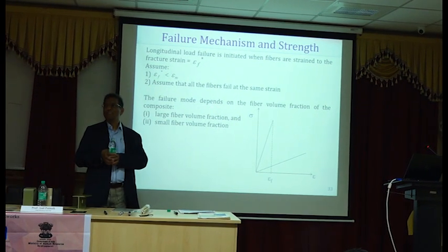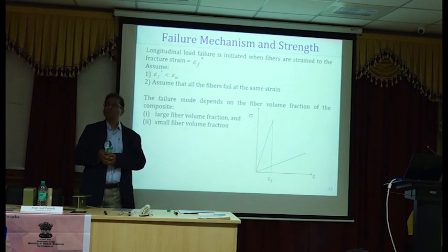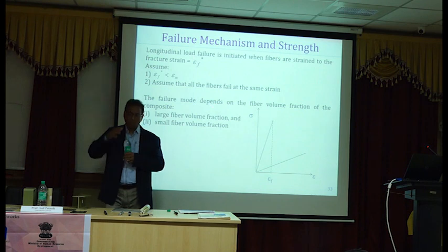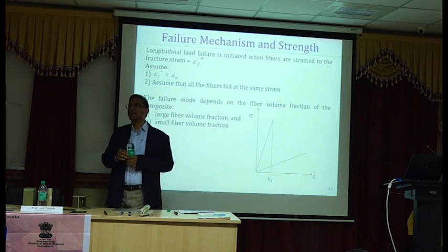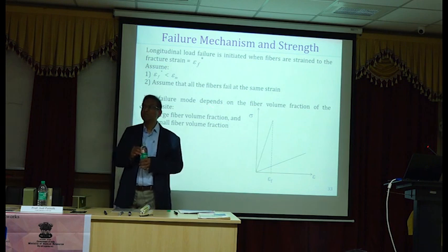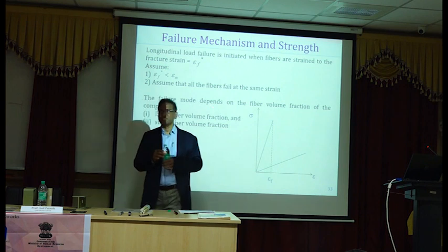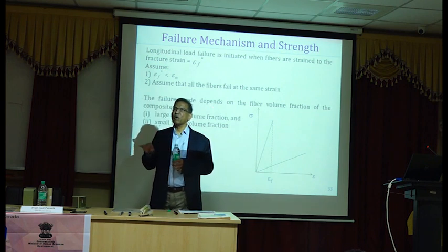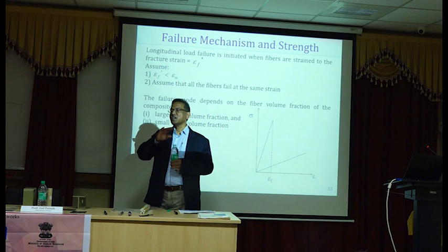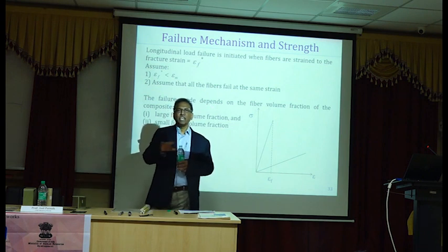One at a time. Shrinkage crack is one. That's for beams. I'm talking about flexure members. Shrinkage cracks and distribution steel are mainly for crack control, but normally they are transverse to the longitudinal direction of the member, right? So in beams we don't provide transverse reinforcement. My question is why, or what's the basis for the minimum reinforcement equation in your beam design?